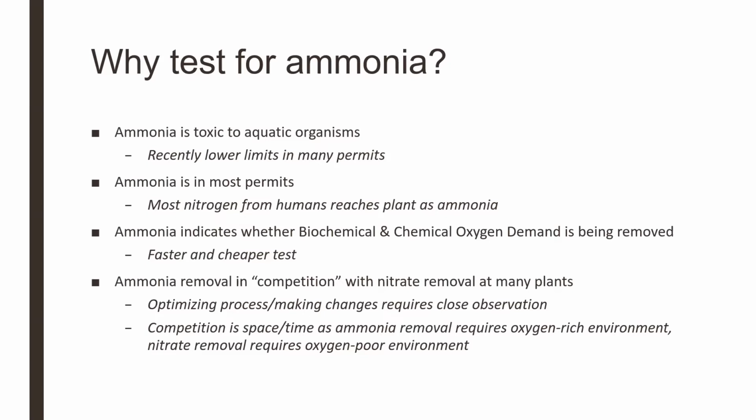Another reason you want to test for ammonia is that it is in competition with nitrate removal at many plants. So depending on your plant layout, there's a little bit of give and take between ammonia and total nitrate removal. So optimizing your process and making changes typically requires close observation. So the main competition between ammonia removal and nitrate removal has to do with both space and time within your treatment facility.